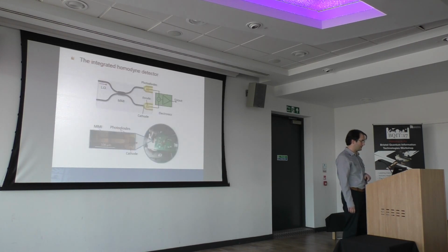What does it look like in an integrated context? Well, the experiment we've done here is 2 single-mode waveguides, a multi-mode interference device, which acts as our 50-50 beam splitter, and finally 2 integrated photodiodes, which I'll talk about in a second.